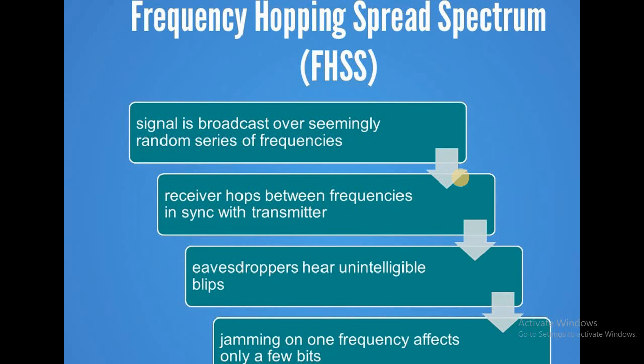Frequency hopping spread spectrum. What is FHSS? FHSS is a method of transmitting radio signals by rapidly switching a carrier among many frequency channels using a pseudo random number or pseudo noise sequence known to both transmitter and receiver. The advantage of the system is that the signal sees a different channel and a different set of interfering signals during each hop, periodically changed according to the PN sequence. It keeps on changing. Transmitter and receiver frequency are in synchronization.